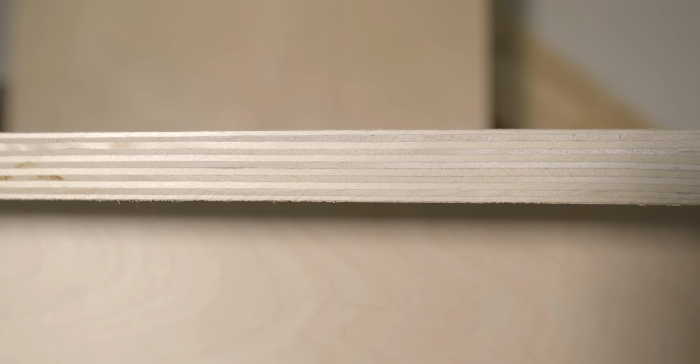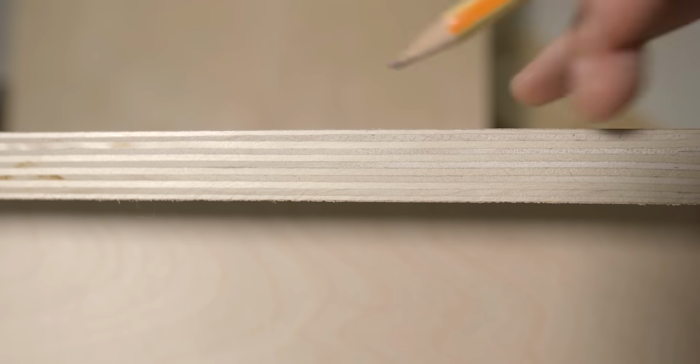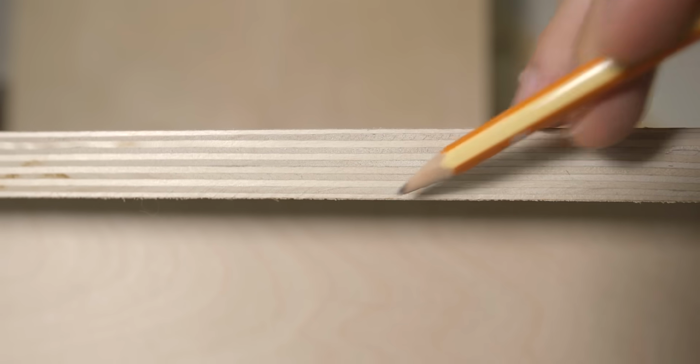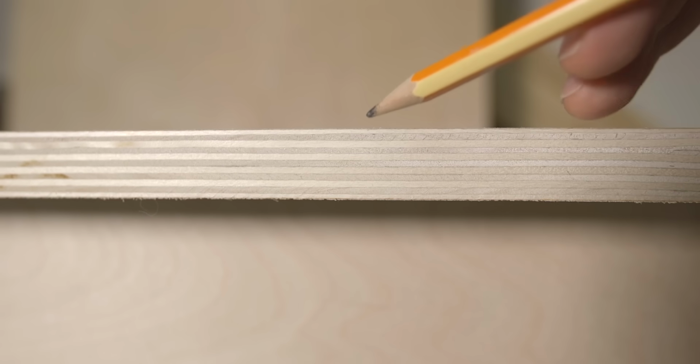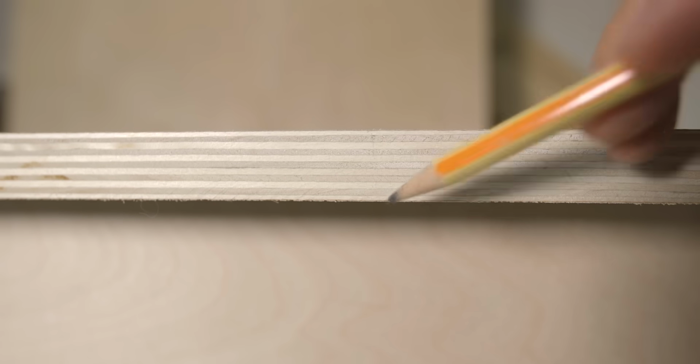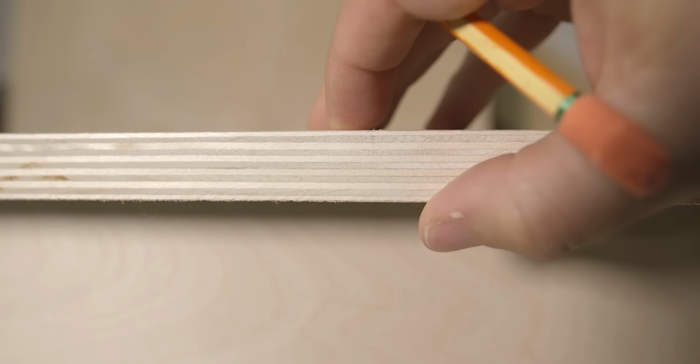The last type of plywood to look at is Baltic birch, and here in the US, Baltic birch might be the highest level or quality of plywood that you can buy. For example, this piece of 13mm or 3/4 inch here in the United States has 2 thin outside veneers and 11 interior plies for a total of 13 plies, making this a very strong and very stable material.